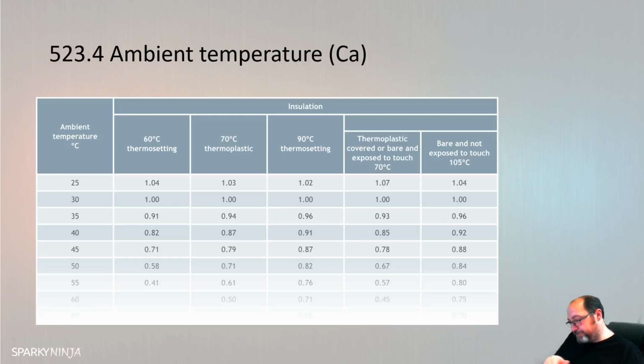We then have a number of formulas in 5.1. There's a formula for single circuits. There's a formula for groups. Overload protection is not required. Other frequencies, etc. But before we go into that, let's look at the rest of these rating factors. So the first one we saw was table 4A1. Not table 4A1, 4B1, which was just after the very large table 4A2. So table 4B1, page 394. That's this on the slide here.